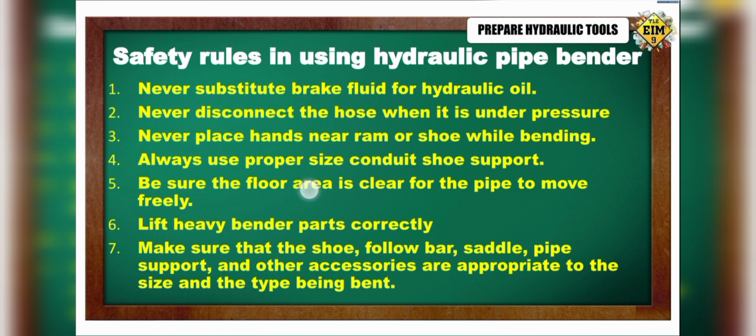And number 4, always use the proper size conduit shoe support. Tatandaan din class na ang ating mga pipe bender ay kailangan palitan yung shoe, o yung mismong part ng hydraulic pipe bender natin na tutulong para mag-bend ng specific size of conduit. So, kung anong size ng conduit ang ating i-bend, yun din dapat ang size ng ating shoe sa ating hydraulic pipe bender.